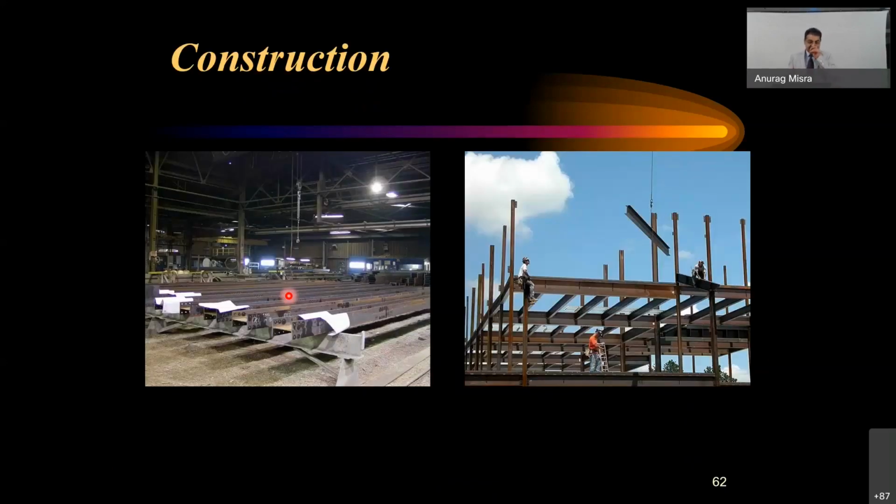The steel building, we come back to the construction of these steel buildings, where you could see that story wise, right now the erection is going on at that place. The moment this frame is completed, you can immediately start erecting the beams on the upper stories. So you have created the complete list of the components, members. All the members are marked, brought to the site, and with the help of cranes, they will be taken to position, and just bolting is done.